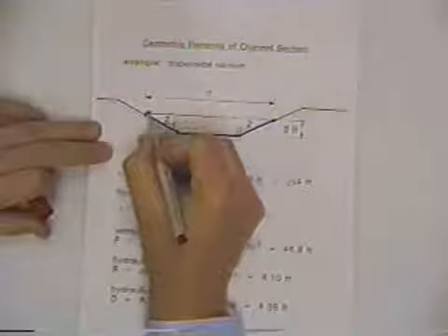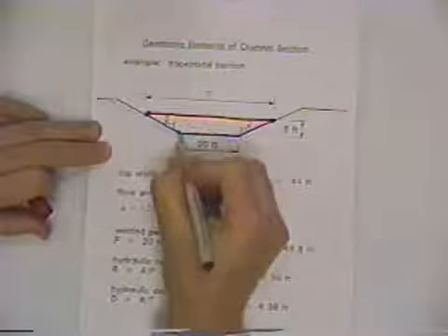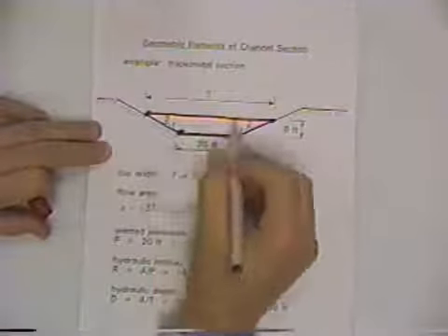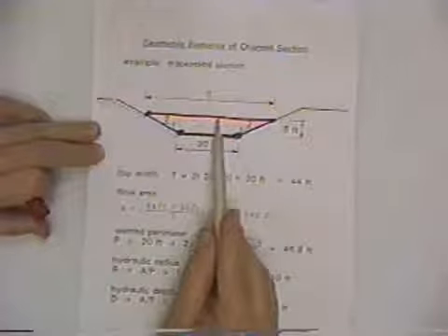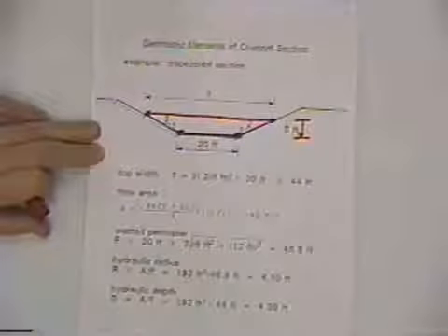And so that's the wetted perimeter, and the flow area to plug into Manning's equation just from geometry would be the top width plus the bottom width divided by 2 times the depth. So we're really out of fluid mechanics into geometry, but geometry is a big part of solving fluid mechanics problems. And so just taking the top width plus bottom width, dividing that by 2, and multiplying by the depth, that would give you a cross-sectional area of flow.